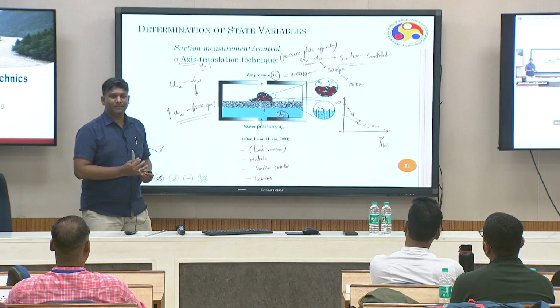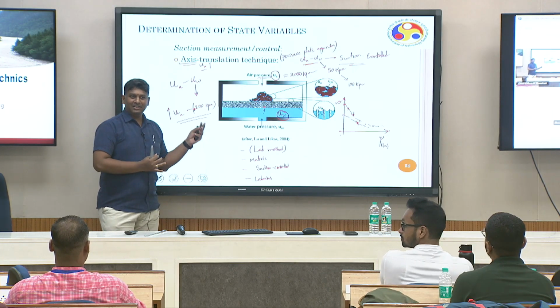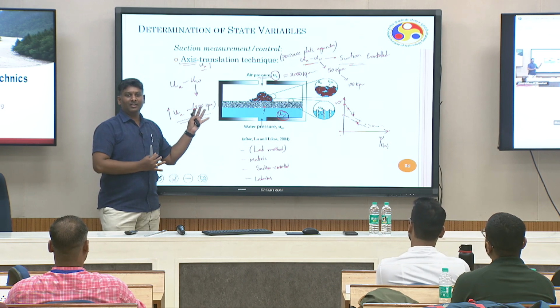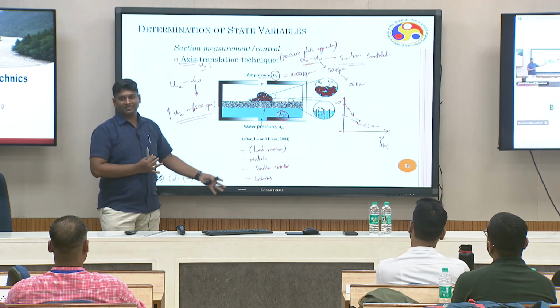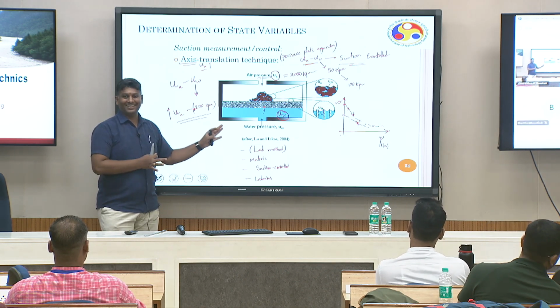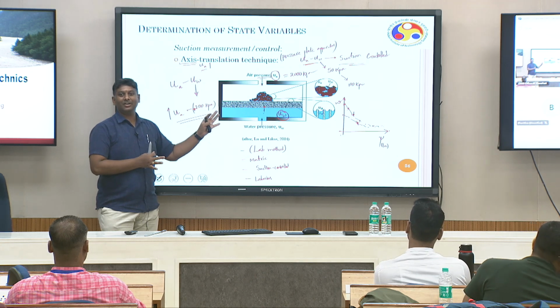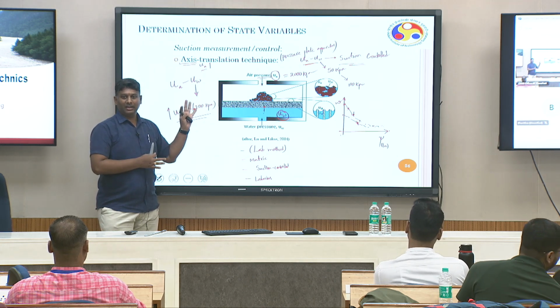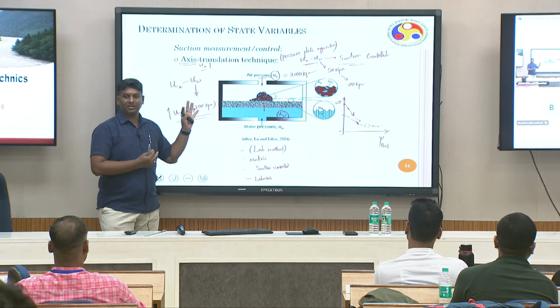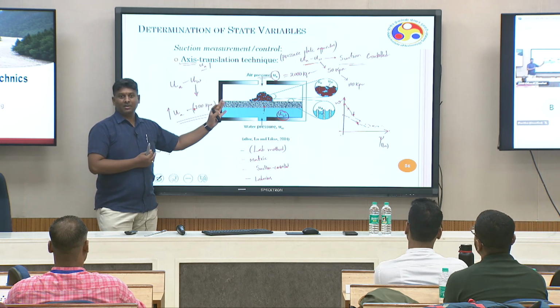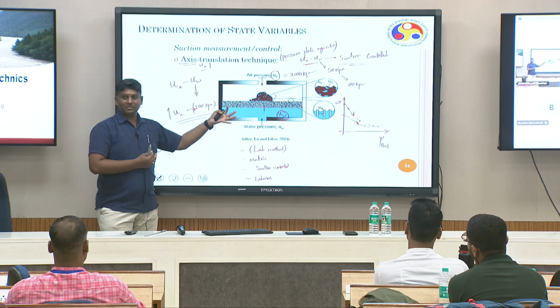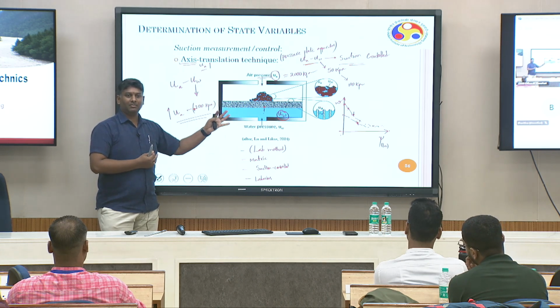Very difficult actually. The advantage is that this method is used for establishing the hydraulic conductivity function. Theoretically it is possible. Theoretically you can establish the hydraulic conductivity function, HCF, K versus psi, or water content. Same method, okay? Outflow technique or something they call it. It's exactly the same method, same equipment, but very, very time consuming and very difficult to do.